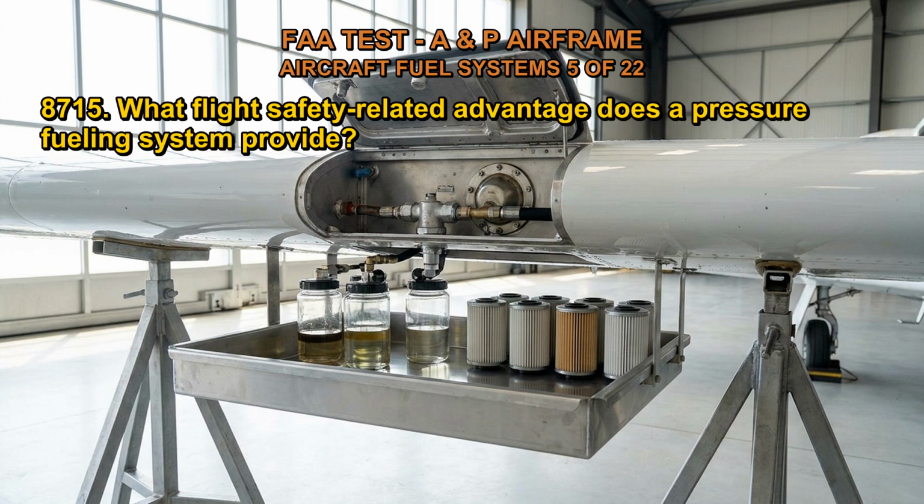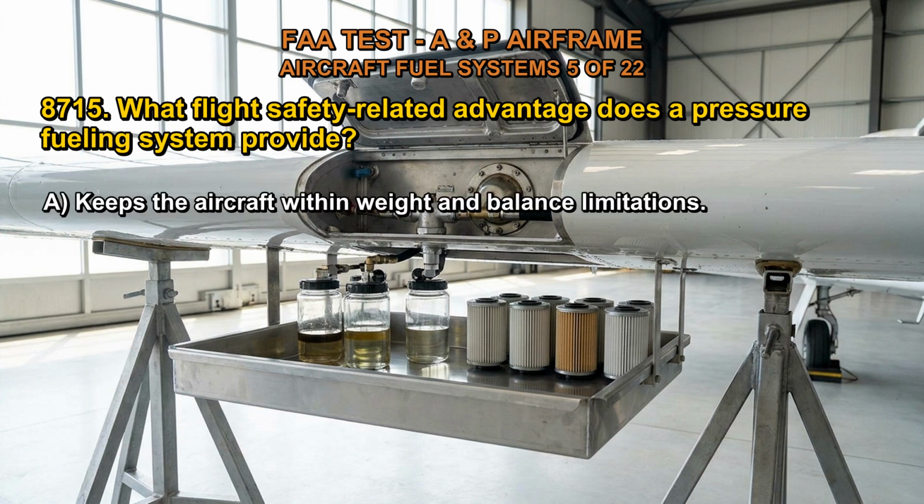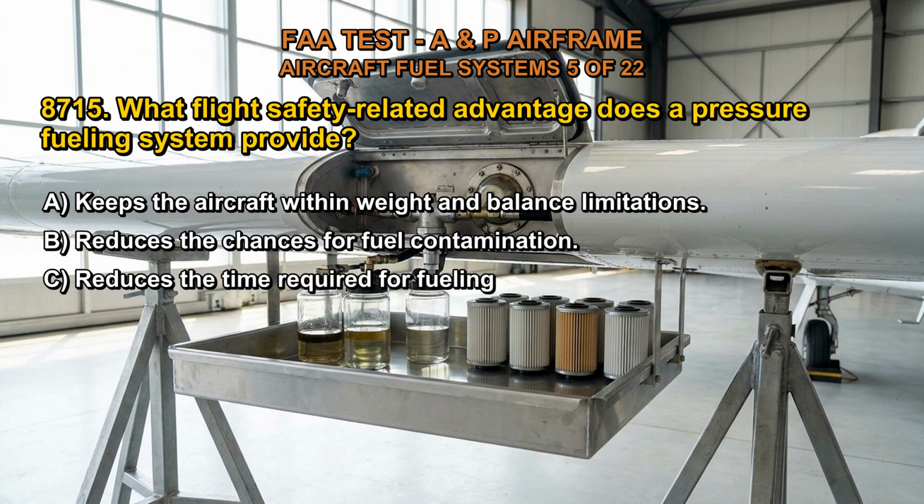8715. What flight safety-related advantage does a pressure fueling system provide? A. Keeps the aircraft within weight and balance limitations. B. Reduces the chances for fuel contamination. C. Reduces the time required for fueling. The correct answer is B.